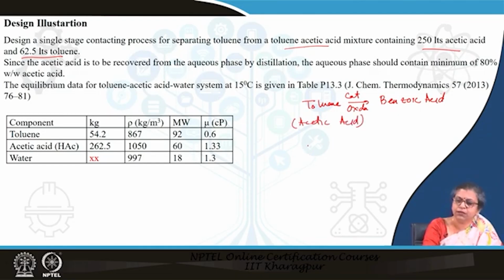So, we started with 250 liters of toluene and 250 liters of acetic acid. The reaction occurred and about 75% conversion of toluene took place. Then we were left with benzoic acid, the unreacted toluene and the acetic acid. This was cooled by putting it in cold water. The benzoic acid crystals separate out,